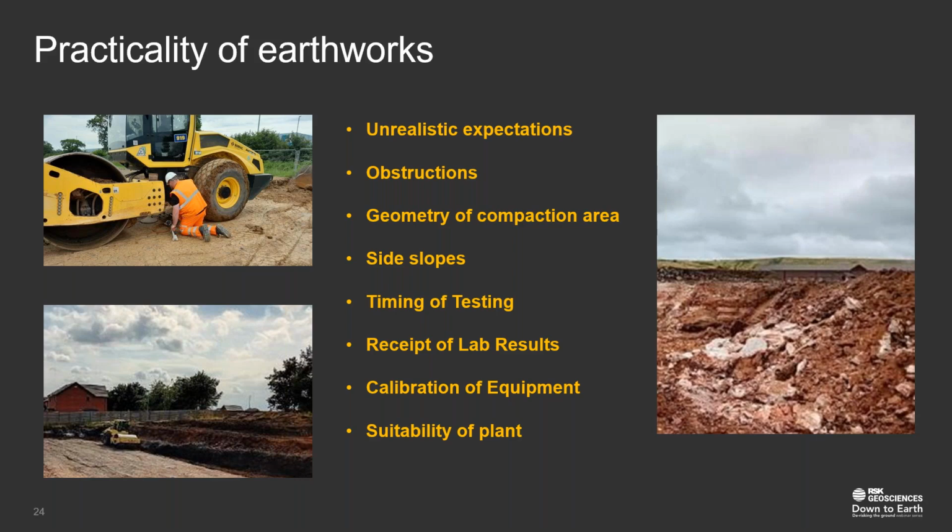Another problem with the practicality of earthworks is sometimes unrealistic expectations. If you've got a site which is really wet and the natural moisture content of the soil is really wet, and you're expecting to get a high degree of compaction out of it, well, you're going to have a problem. You're either going to have to modify the moisture, perhaps using lime, to basically extract some of the moisture from the soil,